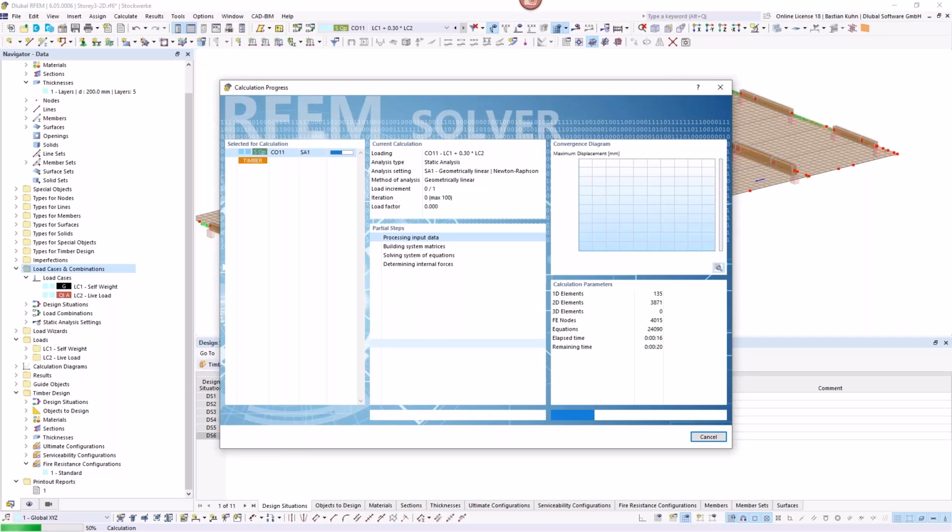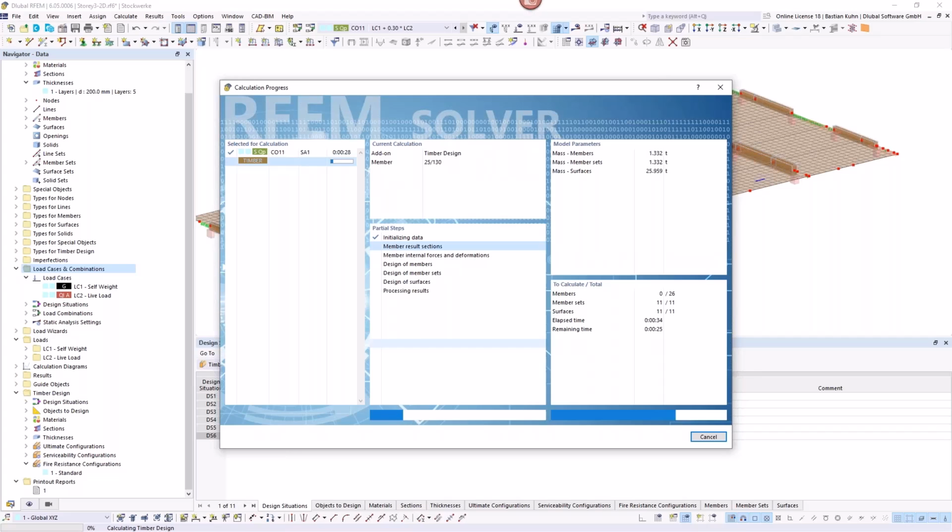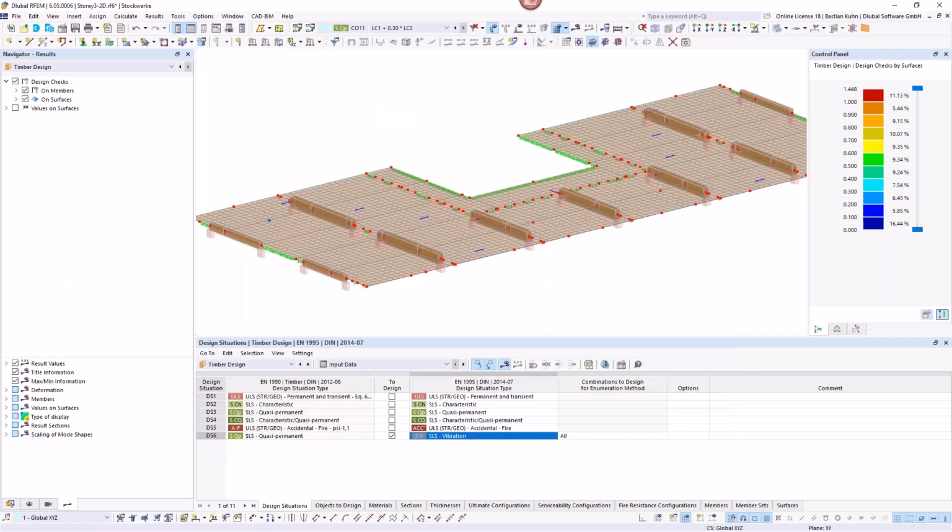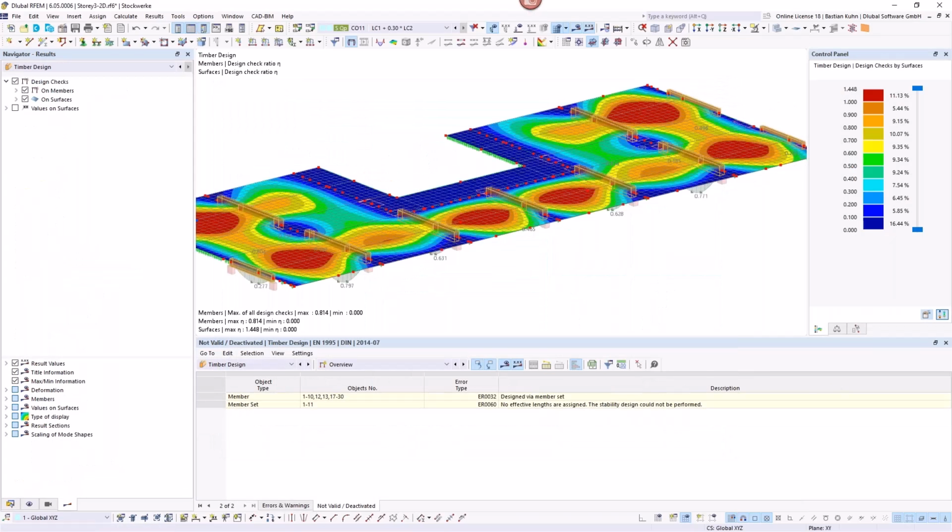That's the point I want to have in here. You know, the simplified vibration analysis is similar to the SLS verification: it looks for the biggest deformation, and this is then divided by the limit deformation of 5 millimeters. I showed it to you in the configuration settings, and you see everything's red.